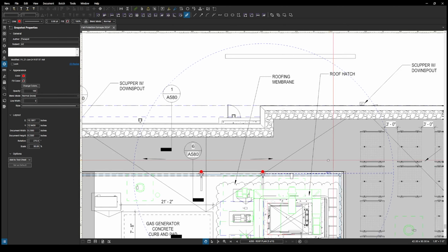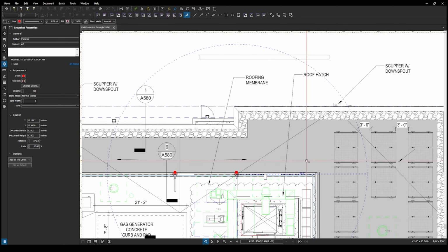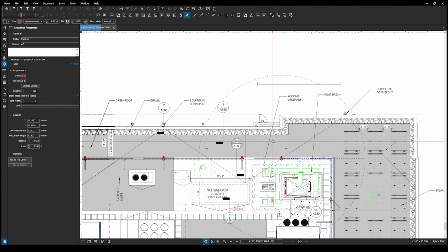And for this case, we're going to assume that this is an 8-inch thick concrete slab. There are all different roof types, but this will allow us to place anchors anywhere we want within reason. Of course, if the structural components of this roof were, say, a steel structure, then we try to match any structural components that already exist or are planned to be placed onto the project. We can weld the anchors onto the existing steel. Fortunately, this isn't always an option, depending on the material the roof and project are made of.